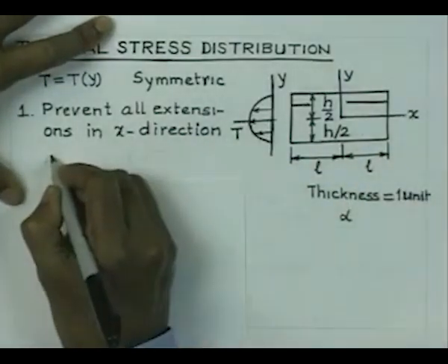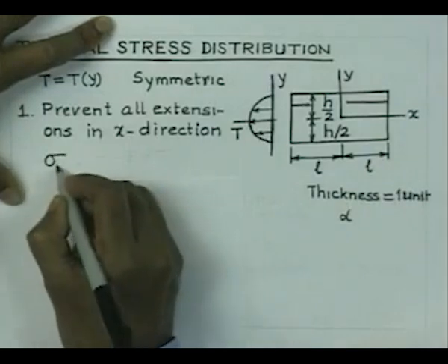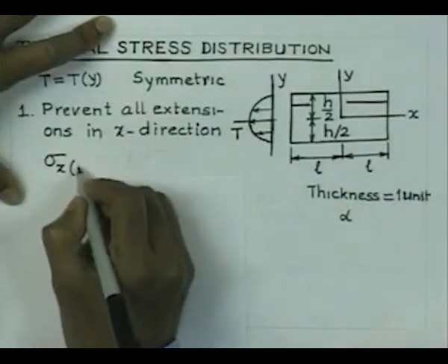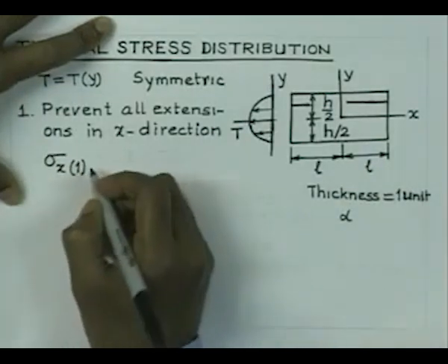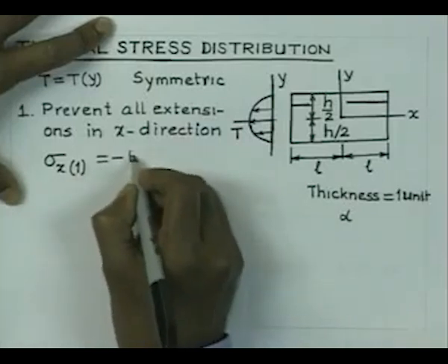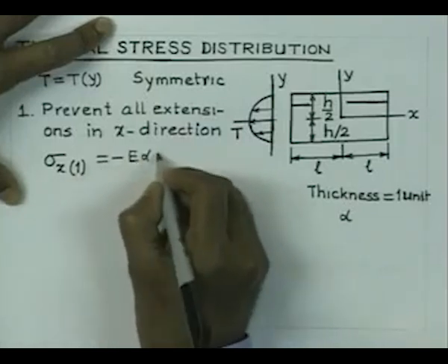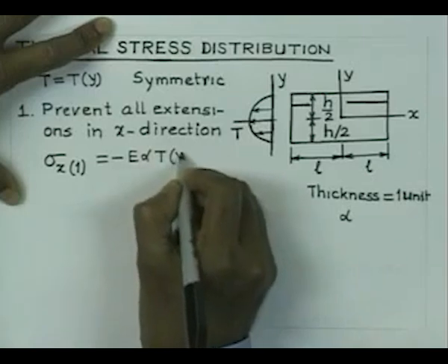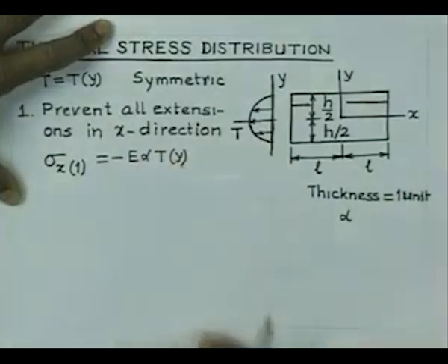Let us indicate that stress to be equal to sigma x1, and this is going to be equal to minus E alpha T, and since T is a function of y, let us write that.